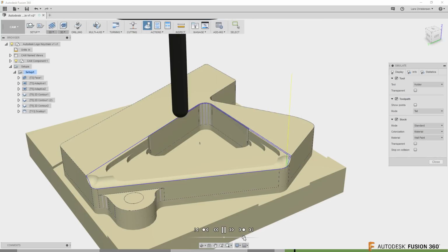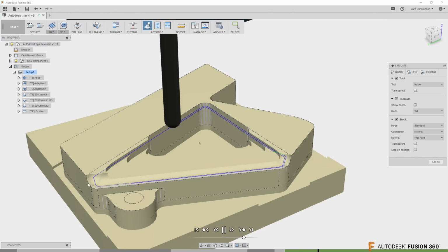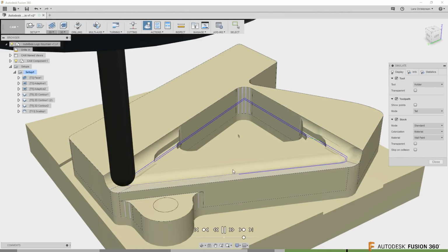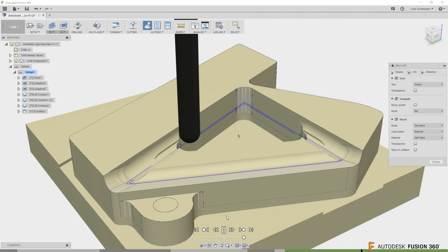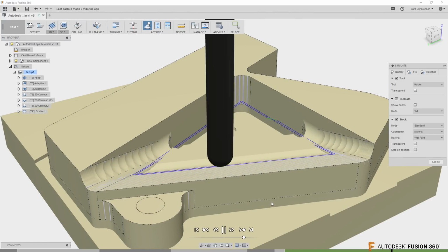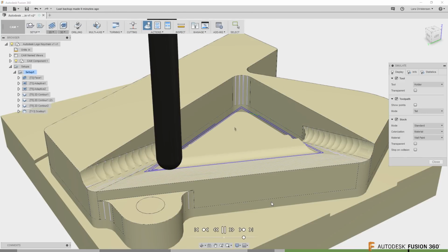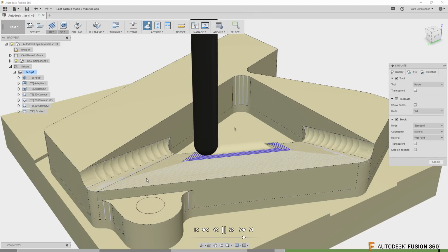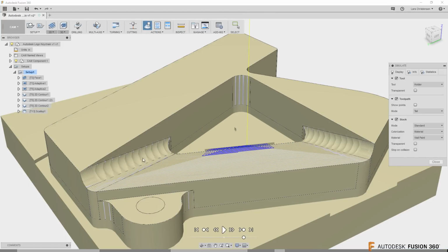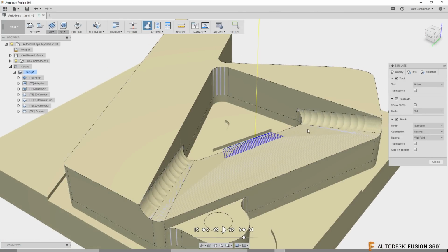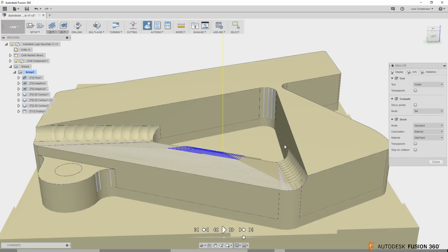So here you will see this pass. I would rough, then I would have a semi cutter where I would leave some stock on the cutter. But now we will see this is actually I think a pretty good pass to clean this up. However, one thing I noticed as we are looking at this is that these areas right in here, I hope you can see that on the two radiuses, that is not great. See how we almost got bite marks in here with this cutter.